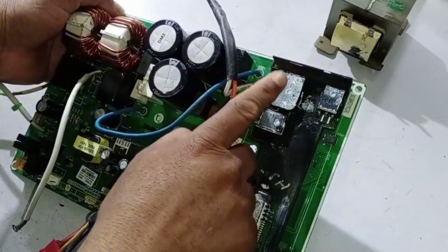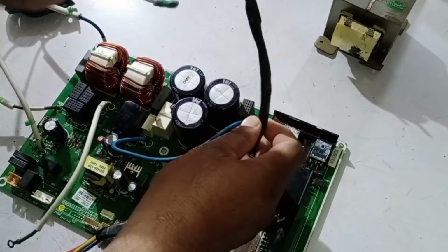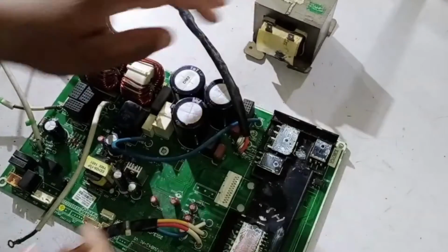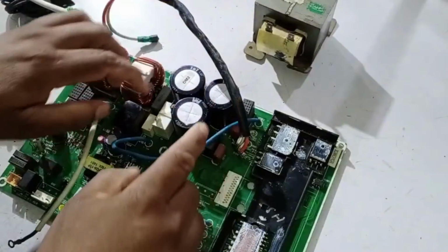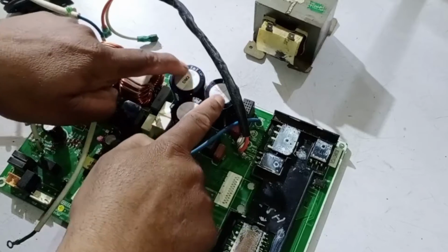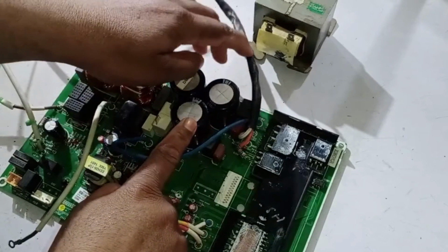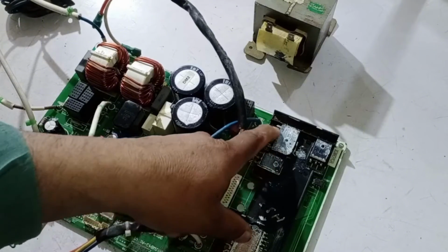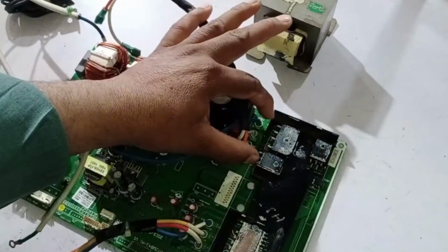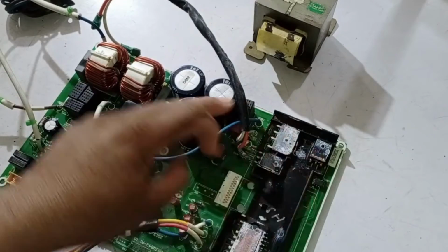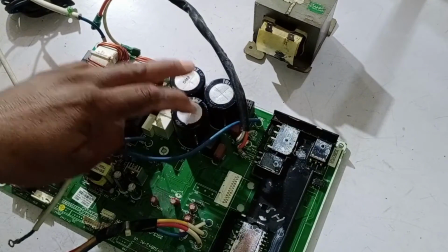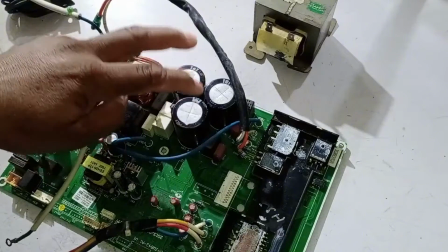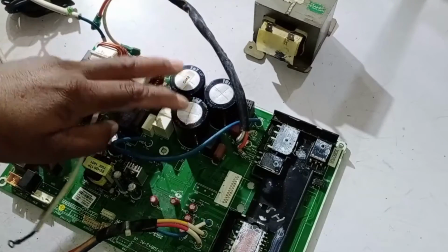If the rectifier is working correctly, the supply then passes through these two wires. These two wires are connected to a reactor. Here, another important component comes into play: 3 large capacitors. These capacitors boost the electricity, meaning they boost the voltages. The input voltages coming to the inner pin of the rectifier are AC 220 volts, and the two outer pins of the rectifier are connected to these capacitors. On these capacitors, there should be 320 volts on standby and 380 volts under working conditions. If you're getting these voltages, that's good.